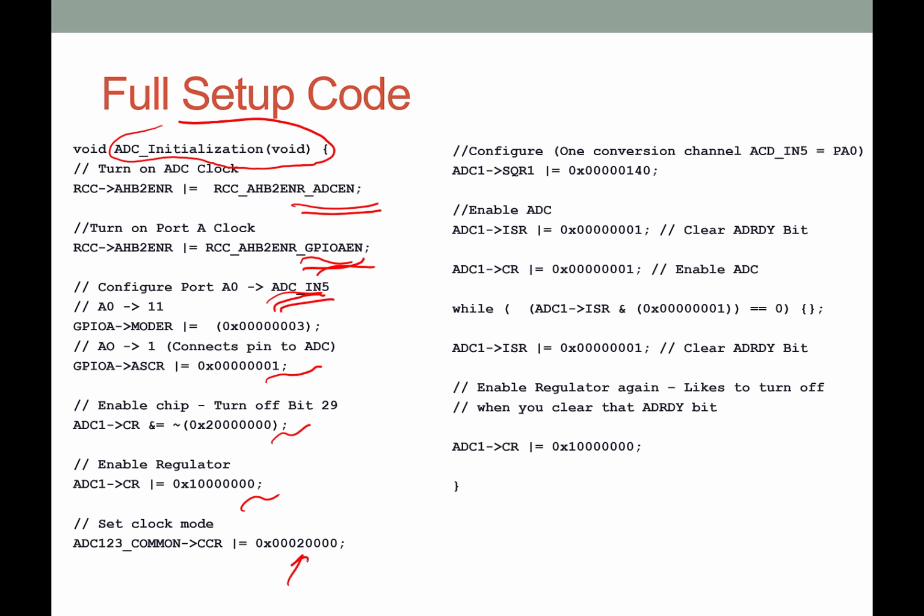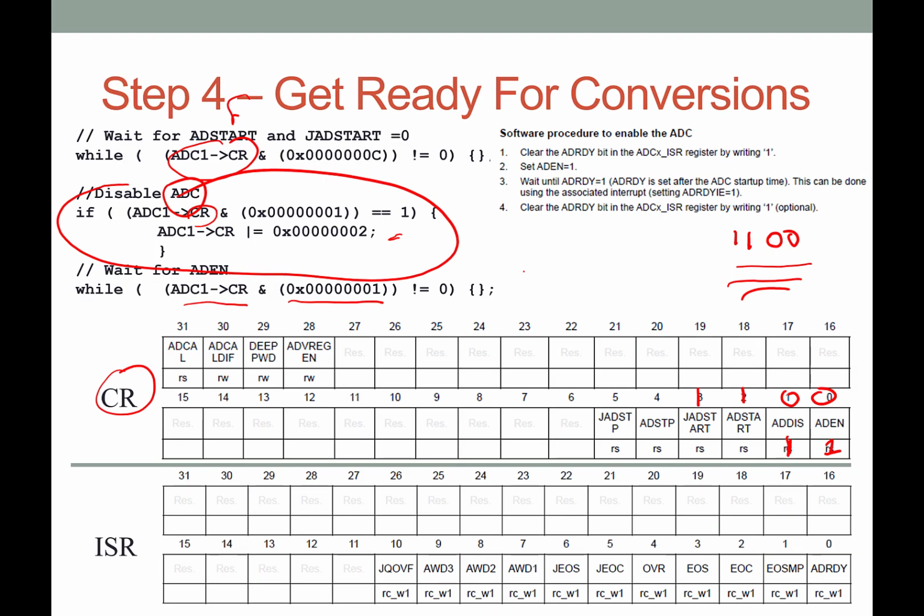Then it says, okay, now what are we going to do? We're going to configure the channel for a single conversion. We already talked about that. We're going to enable the analog to digital converter. Notice it's going to clear that ADRDY bit.